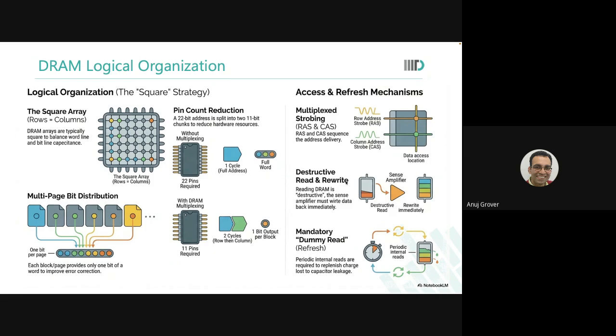And not just a physical phenomenon, also that the DRAMs just store some charge on a capacitor. In SRAMs, there are mechanisms to replenish the latch. There's nothing of that sort in the DRAM, so they are much more susceptible to soft errors. But by storing just 1 bit in one array, we have assured that even if 10, 20, 30 bits get corrupted, they are just 1 bit of each of those 10, 20, 30 words. So the same kind of error correction which you could have done in SRAMs is far more efficient, much more area efficient, power efficient, and overall better.